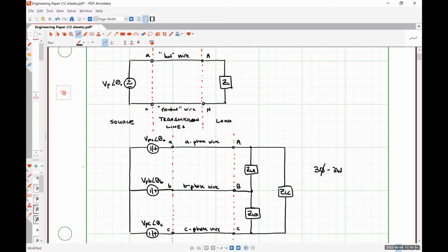And what they do is literally convert a three-phase AC signal into a DC signal using what are called rectifiers, which you'll learn about in your electronics classes next year. And then they take that DC signal and effectively chop it up and make it look like a sinusoid at a different frequency. So anywhere from 45 hertz up to 100 hertz, and you can adjust what frequency that is depending on the settings of the inverter to allow motors to rotate at different speeds.